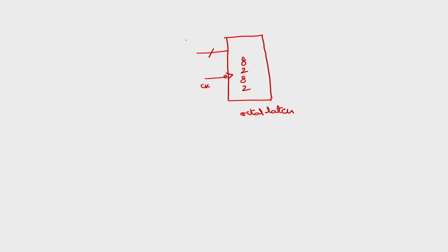In the 8086, a total of 20 lines have to be demultiplexed. Total 20 lines are multiplexed in 8086, out of which 16 are address lines multiplexed with data, and 4 address lines are multiplexed with status. This is AD15 to AD0. Total 16 means there are two 8282 chips here, but I am showing only a single one. So here I will show this as 16 lines.